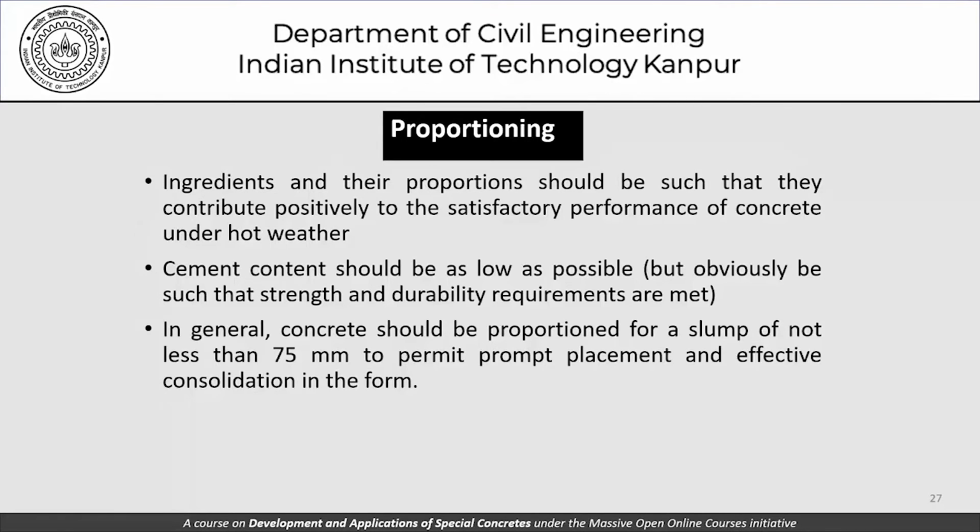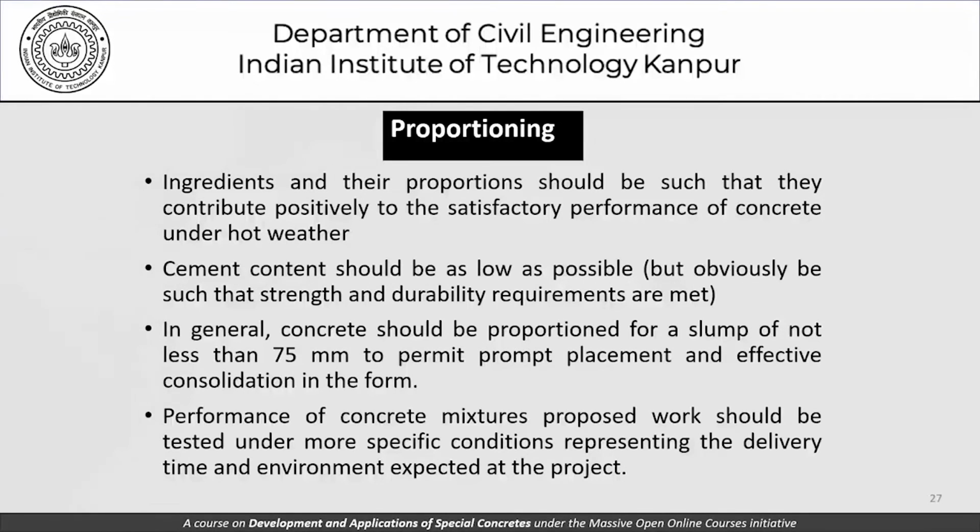form. Performance of concrete mixtures in the proposed work should be tested under more specific conditions representing the delivery time and environment expected at the project. This also is alluding to the importance of mock-up, which is essentially an exercise carried out to duplicate or replicate the conditions at site and then doing a rehearsal.